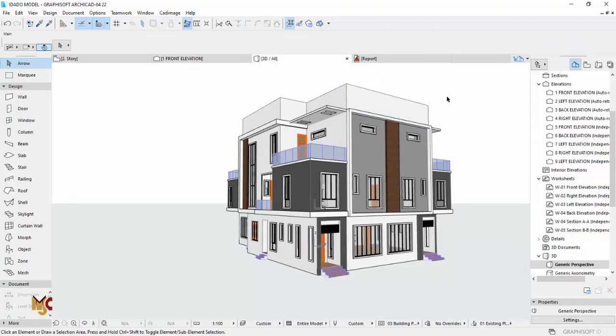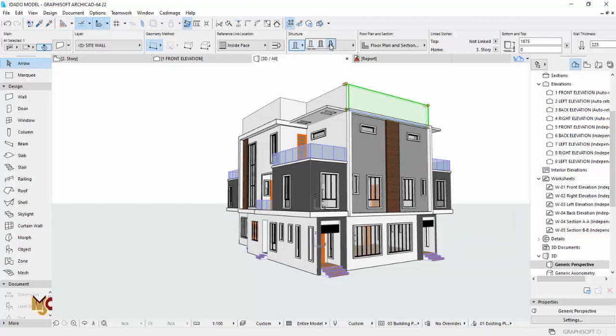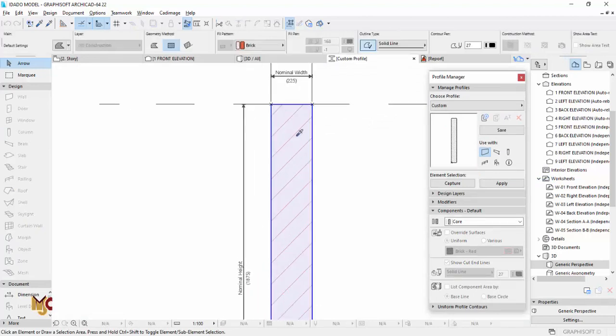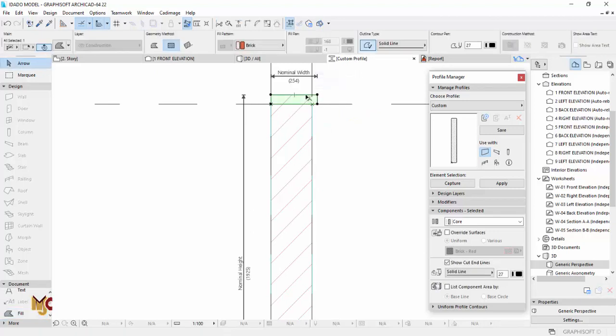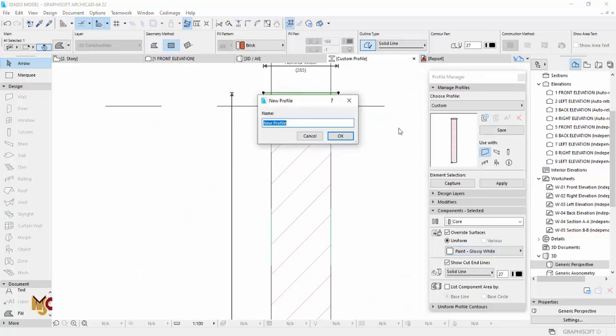And we just place our parapet wall, and it doesn't have a coping, so we are going to make it have a coping by changing it to a complex profile wall so that we can have the edit function when we right click, and then you draw your coping. Get a proper height, do the same overhang, and then we are good to go. Then change the material and save it.